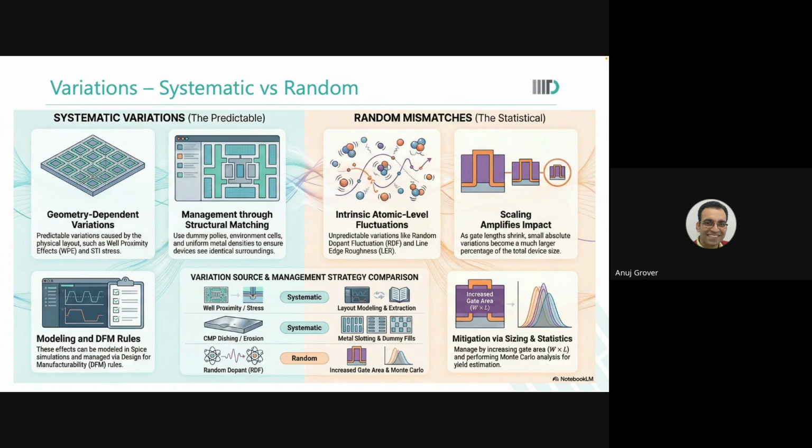So germanium atoms are doped into the silicon lattice because germanium atoms, being larger, cause a different kind of stress. The percentage of doping, 1%, 2%, 5% of germanium in the silicon lattice, causes intrinsic stress inside silicon and can help in improving mobility or degrading it, depending on what you're looking for. Is that okay? So don't think of it as a formula. What you notice is an observation. Don't make it rigid in stone. Are you getting it?